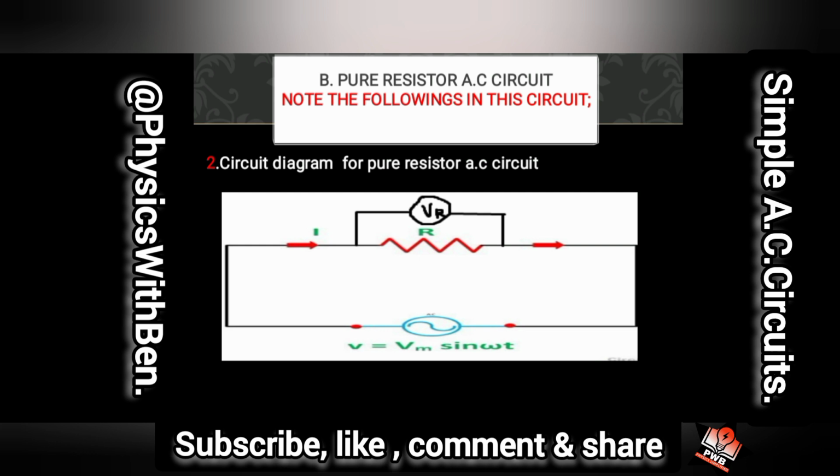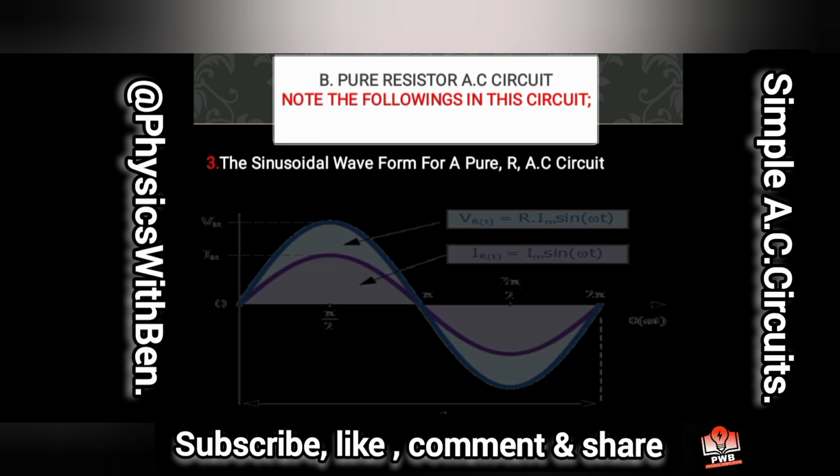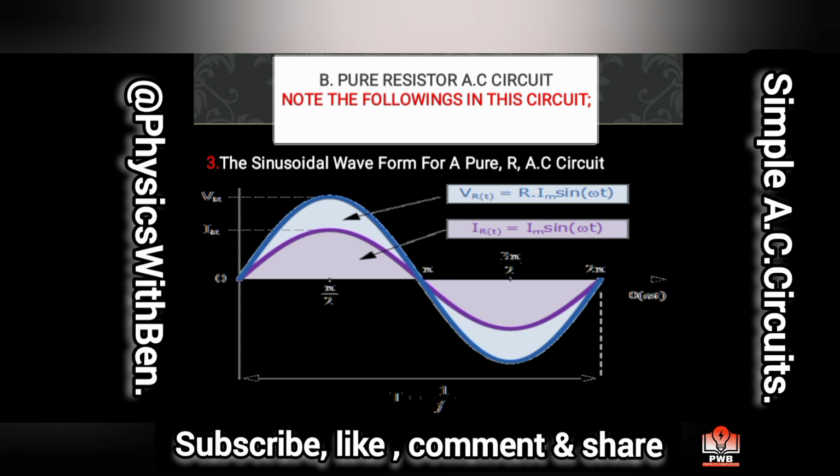There are no polarities. Next up, the examiners may ask you to draw the sinusoidal waveform for a pure AC circuit. And this is how it goes. Here, the blue line stands for the voltage, and then the purple line stands for the current. They are vibrating in phase. You see them going this way and coming this way. Up here are the peak values, here are the zero values, and down here are the minimum values. So you can see that all of them are reaching these places at the same time.